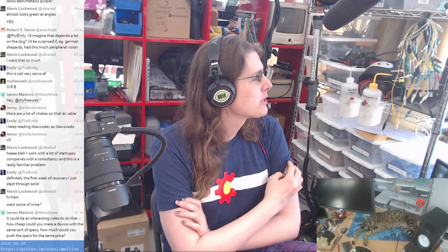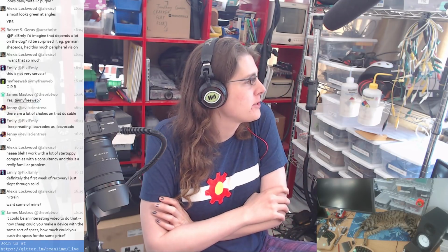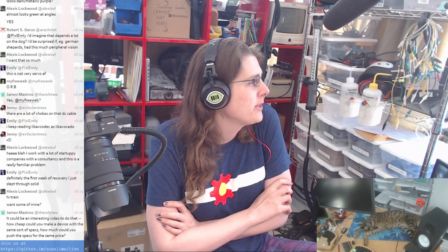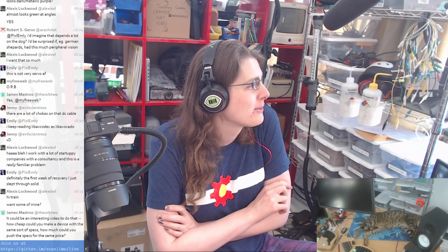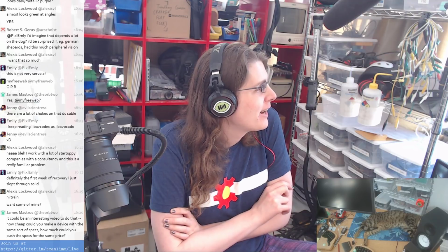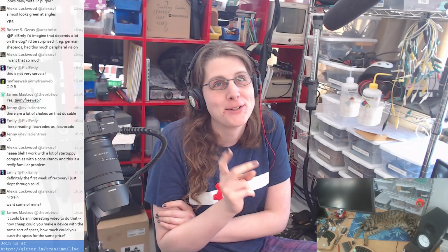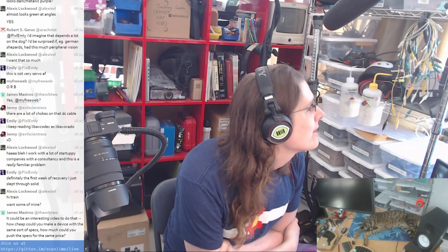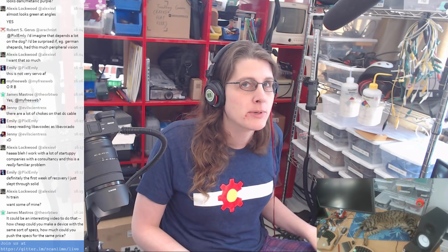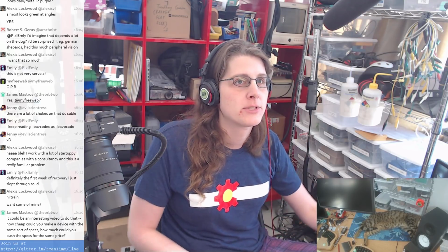There's a question, I don't know if it's actually a question, Grave Gatekeeper on Twitch says that there's 2 things you can do to increase your robot battery. You can use lithium-ion battery to make it last longer, or a power bank. I'm really lost as to the context, but lithium-ion batteries are usually what you'd find inside a power bank. I don't know what kind of robot you're talking about, though. A lot of robots you'd need to draw more current than power banks could safely deliver. Depends on your power bank, of course. There are fancy power banks now that are designed for laptops, but a lot of power banks only really want to give you like 10 watts, whereas robots often need to run higher loads than that.